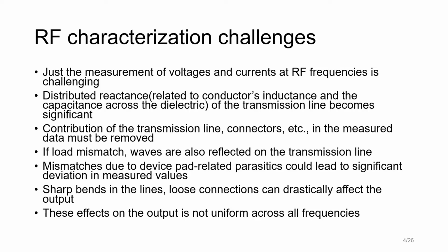The reactance and capacitance associated with the cables respond to the RF signals. So what happens is that the cable, whose role is just to carry a signal from one end to the other, itself begins to contribute to the response as seen by the measuring instruments. So not only does the measuring instrument see the response of the device, but in addition to it, it also sees the response of the cable.